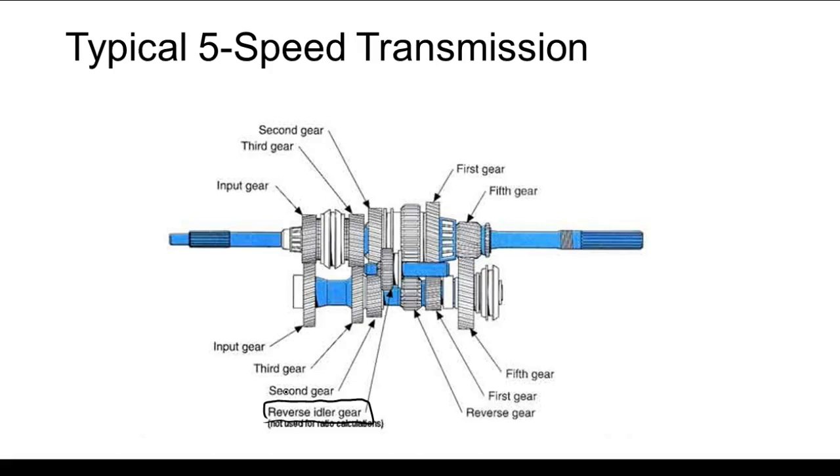But every one of these gears is going to reverse the rotation unless I put what between my drive and my driven? An idler. So this is what happens when you go to reverse. It switches that idler in. I don't know which gear it uses, I think it uses first gear. You get a lot of torque in reverse, but you get a very low speed, right?